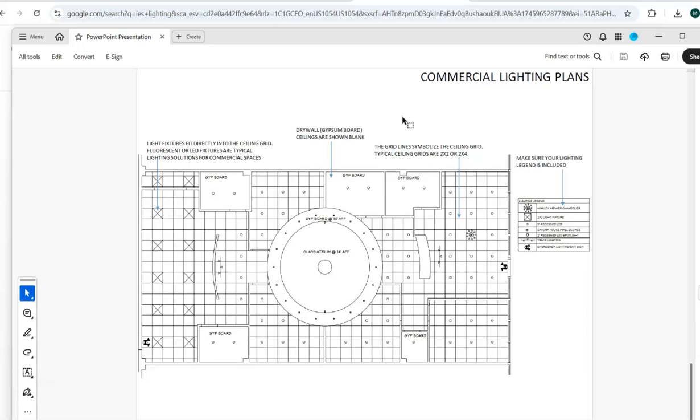Don't place your ambient fixtures too close to the walls. If you put them too close, they will start creating shadows or become wall washers. That's a different layer; a wall washer is a decorative or accent layer, where you might need it, as opposed to your general ambient lighting. So make sure you don't place your fixtures too close to walls, and don't forget the small spaces, closets and pantries. Those need light as well.